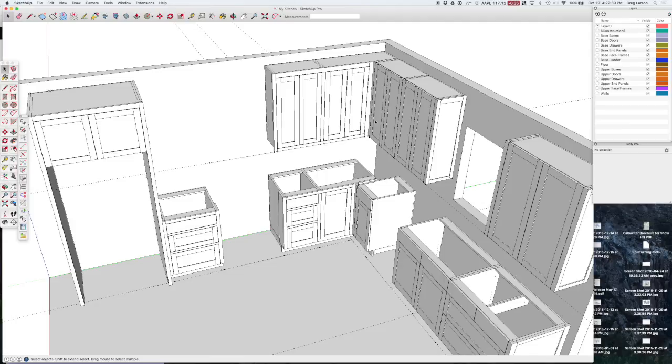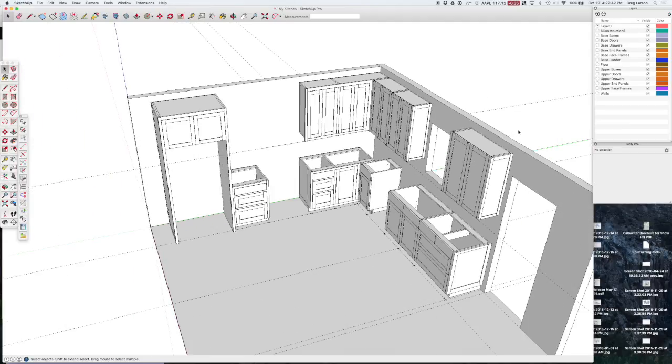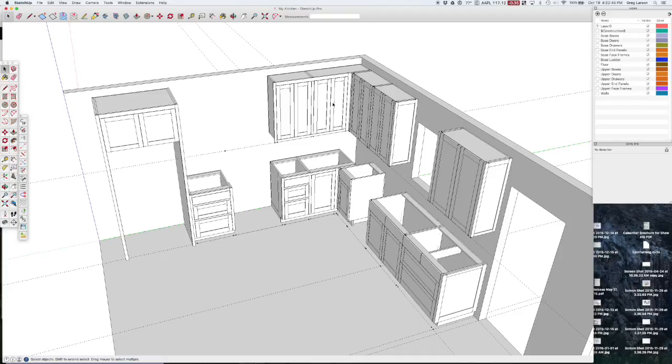So that's pretty powerful. Again, if I wanted to go to another file and pull in a cabinet that was made with this version of CabWriter, and I just paste it in here somewhere, grab a piece of it, and use this tool over here, then I would be able to pull in that cabinet style from the other file. This makes every single file I've ever done essentially a library that I can always draw from. If I did something unique in there, I can pull those settings back in.